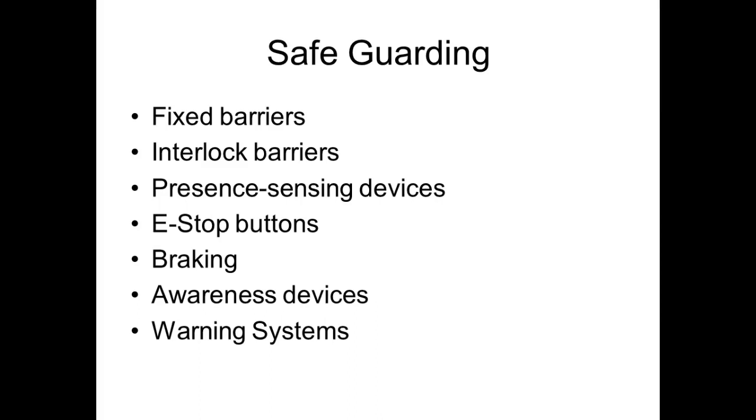It still needs power on a lot of stuff. The E-stop button doesn't necessarily remove power. A lot of people say if you hit an E-stop, it removes power. Is that true? No, it's an E-stop. It's not an E-turn-it-off. It's an E-stop. Y'all understand that? So just because you hit the E-stop doesn't mean everything's going to turn off. The robot will brake. If I want to turn off power, then I find the power disconnect and I turn it off and lock it out, right? Y'all understand that?